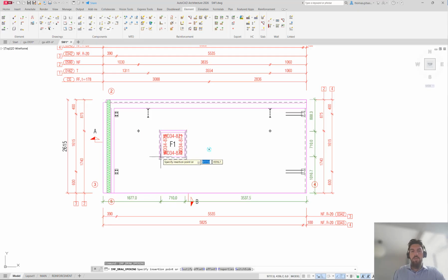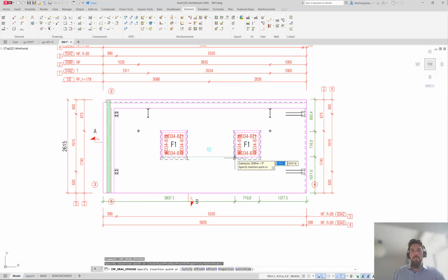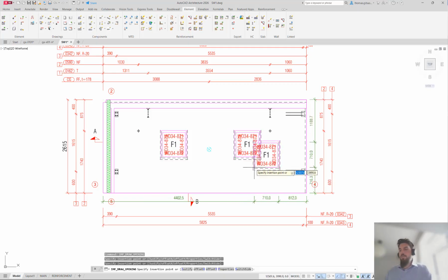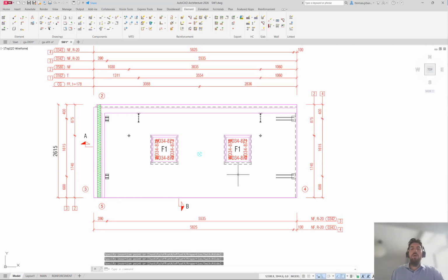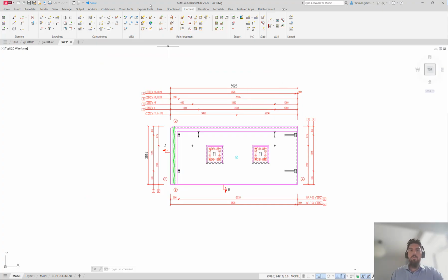So I want to place one here on the 1710 or something, right? And then I'm going to place this also here, the same elevation. See, you cannot make a mistake here. You can also write what you want, and you place those two windows. So the only thing you have to do now is basically press a button here, meaning save. The dimensions will adjust. You don't have to do any manual work in the dimensions. So the dimensions will adjust